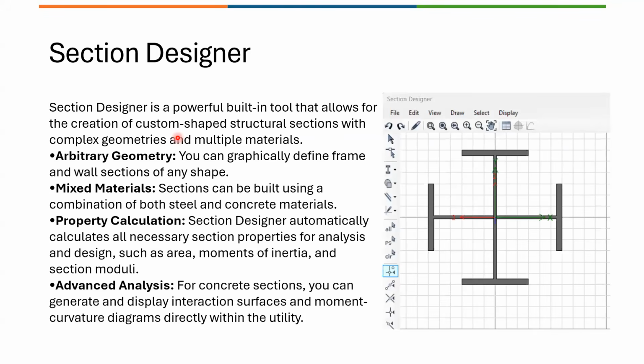We have standard importable section properties for frames, beams, columns, braces, etc. And then standard shell sections for defining the floor slab, walls, etc. We also have a special section designer in case you want to define an arbitrary geometry, like, for example, a star column. You can see that in the image, and it can be a composite.